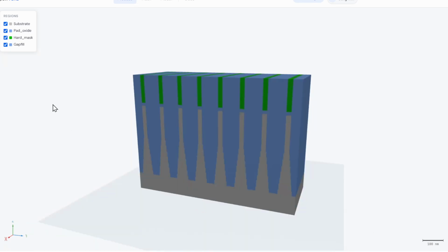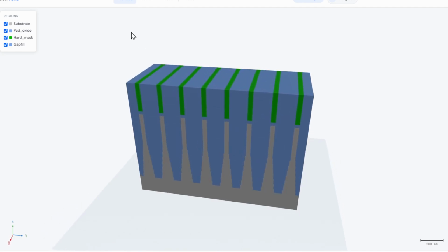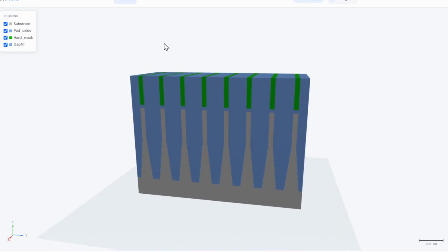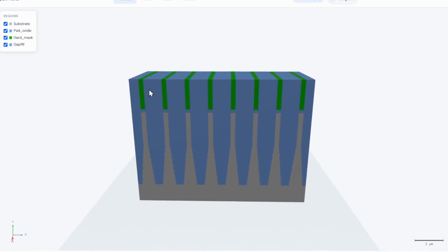First, by using chemical mechanical polishing, CMP, silicon dioxide is removed. So from the top of this structure, we do CMP, and once it arrives at a different material, here given as silicon nitride, it can detect the arrival of new material. Then we can stop the polishing step. So we will have quite a planarized structure as shown here.